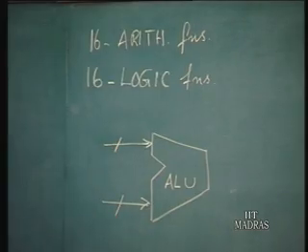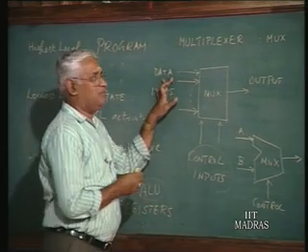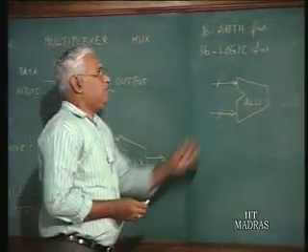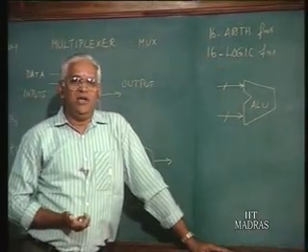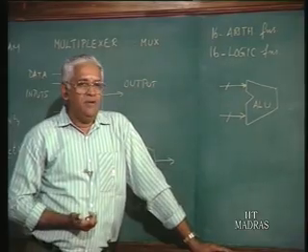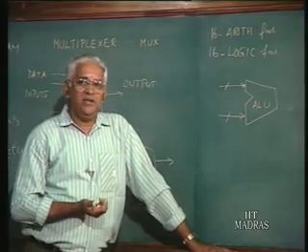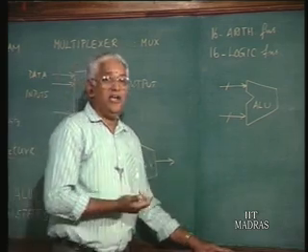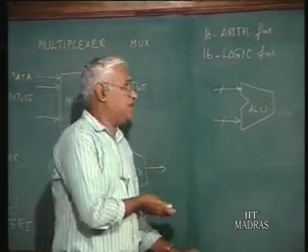In this particular one I was just mentioning data input, we are not talking about the size. Now, in the case of ALU we have to talk about that too, because one of the arithmetic functions can be addition. When we talk about addition, then we have to indicate whether it is a 4-bit addition, 8-bit addition. So, that 4-bit or 8-bit actually refers to the size of the data.